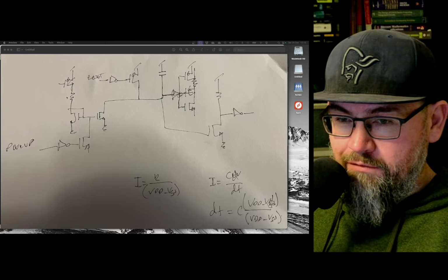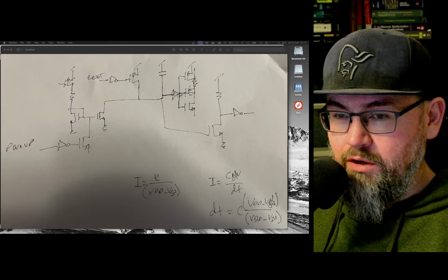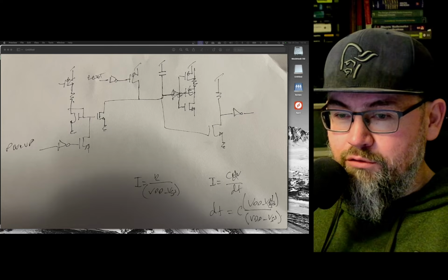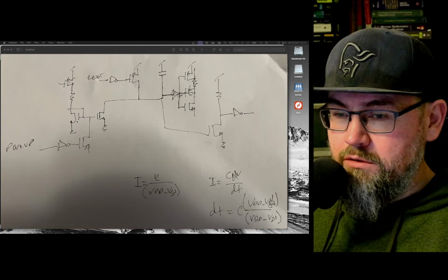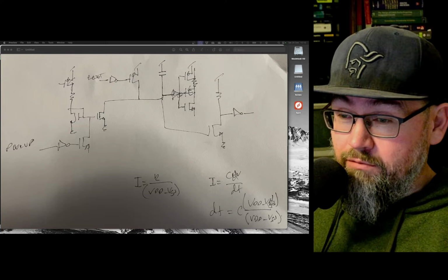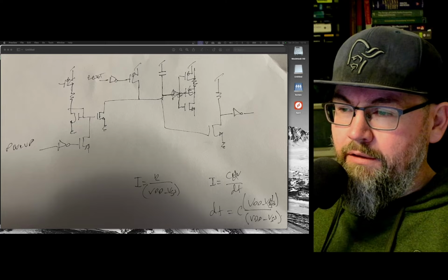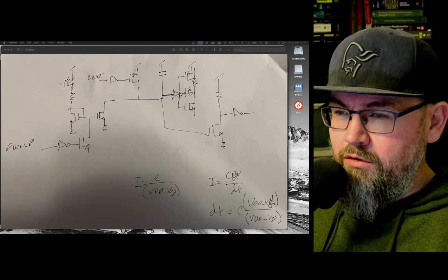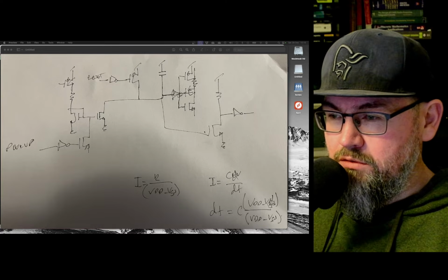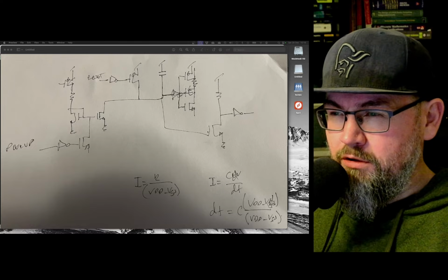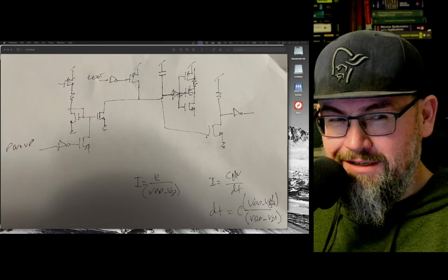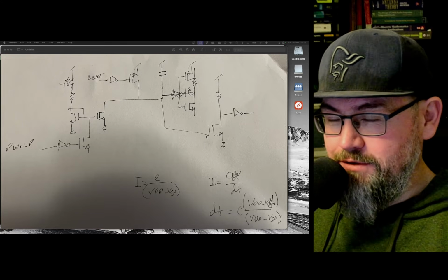So the idea is, if I take a resistor connected to VDD through a PMOS, this would need to be connected to the power up to turn it on, and put that into a NMOS, mirror that current, and then put that current into a capacitor charging down from VDD. Then at some point that should turn off, and that should be related to the VGS of this transistor. And the VGS of the transistor is going to go down with, sorry, not with frequency, with temperature.